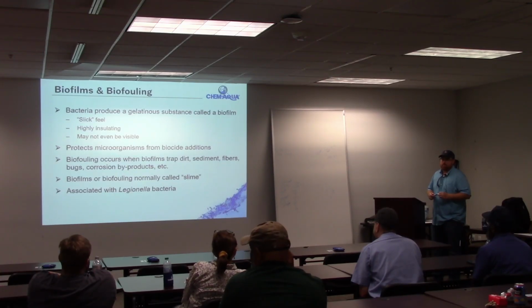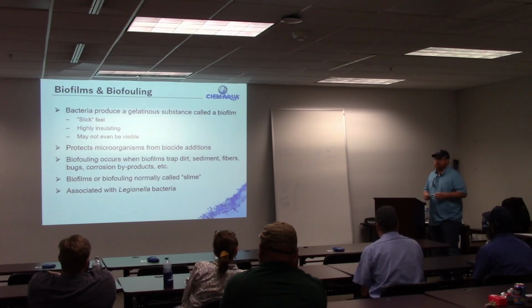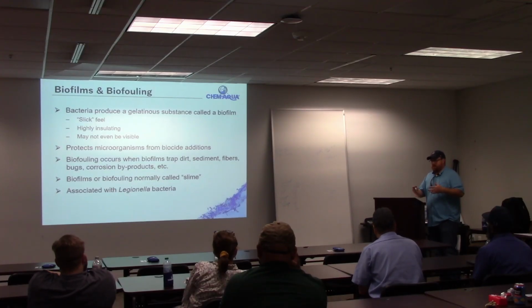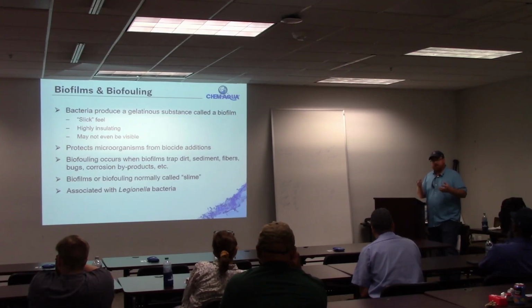There's a lot of dead legs, correct? Yeah, dead legs, there's a lot of problems. Dead legs are a huge problem. One of the big problems with dead legs or offline systems is that bacteria is just sitting there, it's stagnant, it can grow, and like I said, with a pump cavitating and shaking a pipe, that can cause biofilms to break up and Legionella to be released.